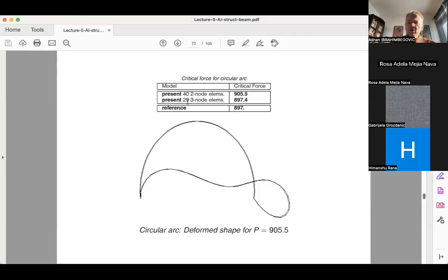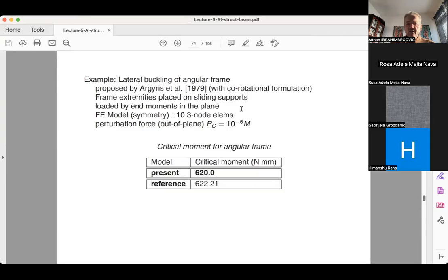Two of them are blocked with a boundary condition, one being built in, the other one being simple support. So solving the same number of equations, but here you're getting almost exact result. Well, it's not so bad either, but this one is even better because you have a better representation of the curvilinear geometry, which is spherical in this particular case.